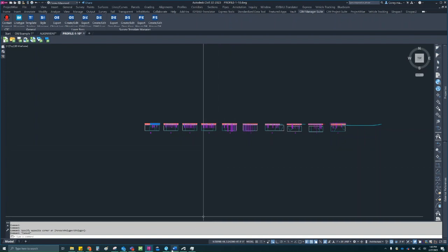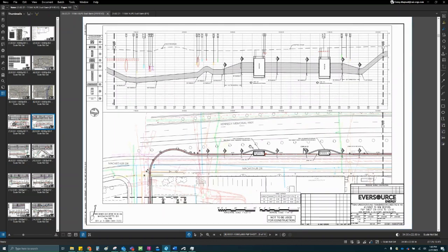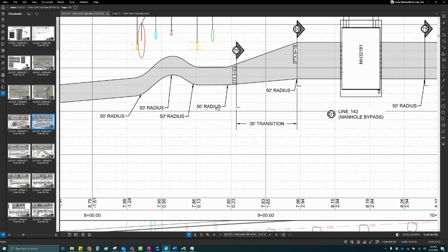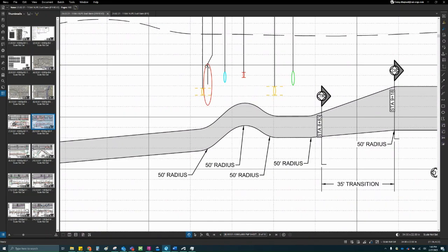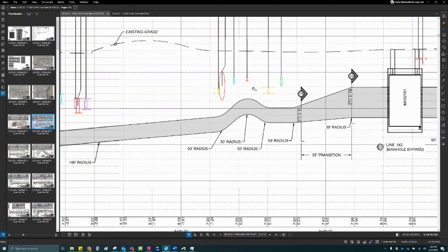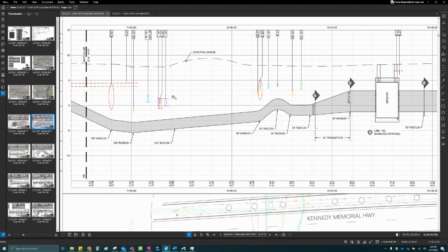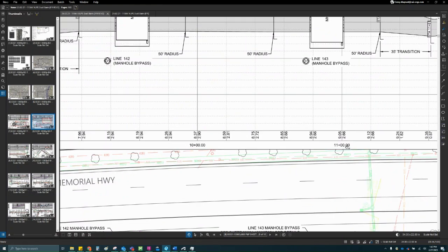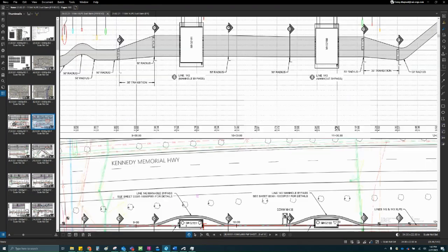And so you can imagine that on a set of plans of this nature, with constant updates, updating all of the station callouts and radius callouts and all of the various pipe networks and offset pipes, and their labels and elevations, accurately projecting the existing grade above the duct bank. All of these things would be very tedious and time consuming. And anytime that there was a change horizontally, that would affect everything downstream, both horizontally and vertically. The placement of all the manholes, the stationing of all of your profiles, and the elevation shown would all have to be individually updated.